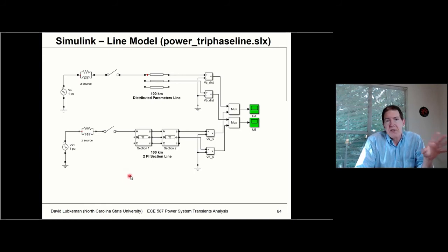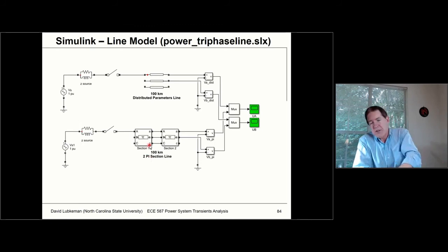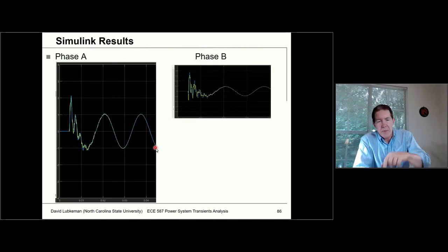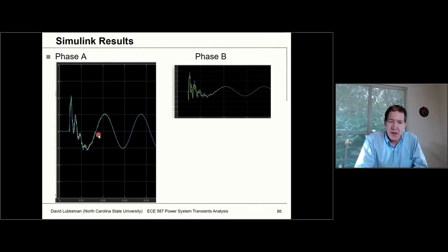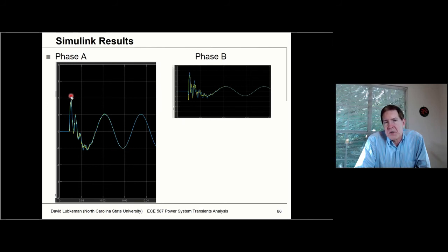So between the inductance and capacitance in the circuit, you're going to see this transient, just like you do with any other transient. We could actually do some calculations where we switch a source on. We could have modeled this with two capacitors and probably an inductance in this case. And this is basically what you see. This voltage doubling effect is something we'll see when we talk about distributed parameters. But this is definitely an overvoltage again.